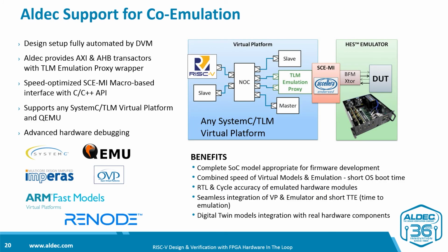Let me summarize the hybrid co-emulation case. If you decide to go with a virtual platform, Aldec can provide you extended support of such hybrid co-emulation. Hardware model setup is fully automated by the DVM tool, so you don't need to be an expert in FPGA. The HES board integrates with virtual platforms through standard interfaces, and Aldec provides AMBA AXI and AHB transactors, which are very often applicable in SoC projects.